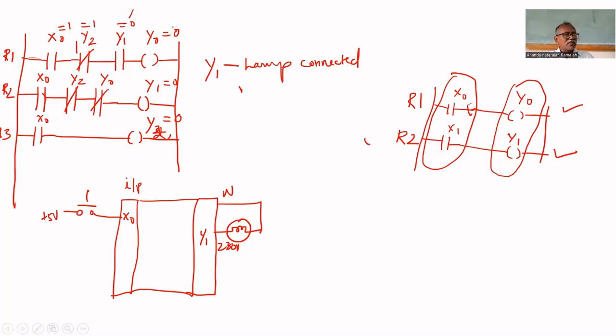During that time, let us assume that this program will be executed 30 times, because to execute the entire program takes 1 millisecond. How long are you pressing the key? 30 milliseconds.